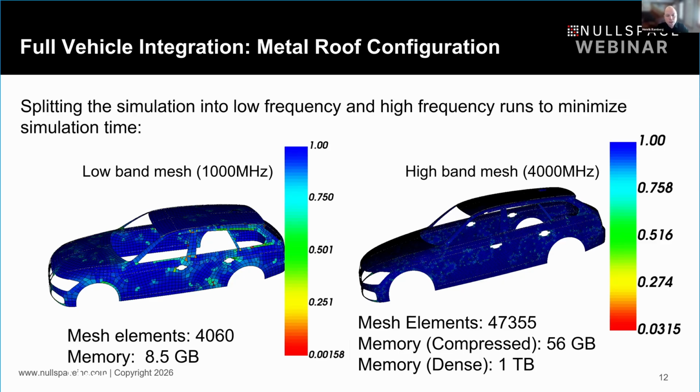If you have a 1 here, where you have the blue curves, that means you have a perfectly square mesh cell, and everything below 1 deviates from that perfect square. But don't get nervous here. What we are seeing here is a perfectly fine mesh, but it's a really good checking point that we have in Nullspace, where we can turn on this mesh quality view.